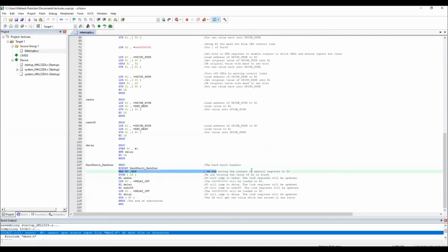So there are certain things that we do, something like this is coming from a main function. Even though the system itself, the core itself, during the interrupt handling process will put things into the stack, something like register R0 and the link register, the program counter, and some other registers like R12 to R15. I think they put into the stack for safety.